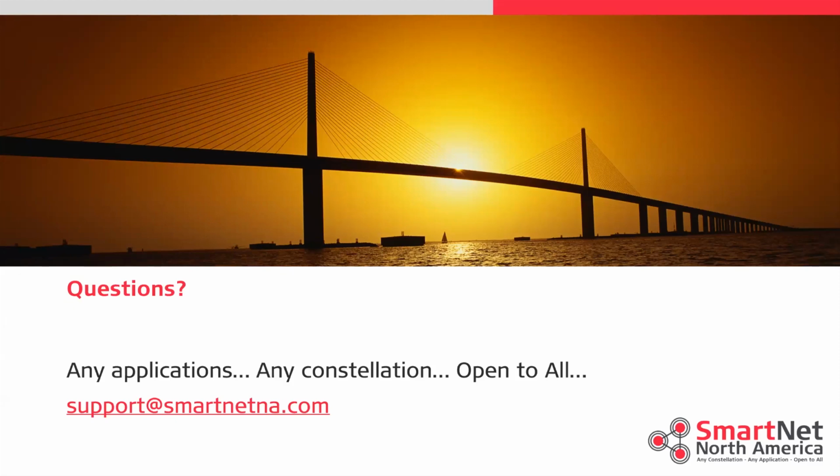Can you elaborate on a suggestion of creating a localization for projects that need to use old coordinates? Thanks. If you don't know how to do localization, a calibration, or transformation, I encourage you to talk to your hardware rep that sold you or trained you on how to use your hardware, should you want to stay on the old coordinates past spring, or need to relocalize or work. If you're an IGS reference frame user or something like that, we probably need you to drop a support ticket in.